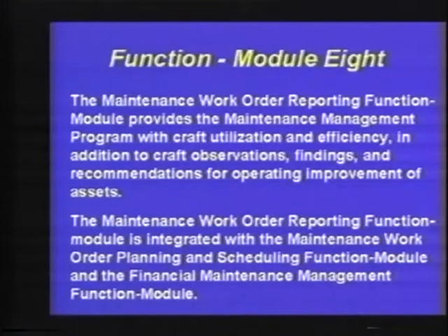The third paragraph establishes the ability, if it is in CMMS, to define the craft efficiency while on the job, and also craft utilization. And we do have in this section another formula which addresses the craft efficiency, and utilization is nothing more than summarizing all of the time elements by sequence or operation number that a craft person is spending on the job.